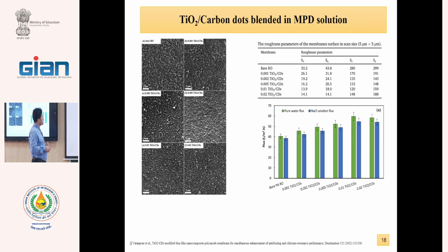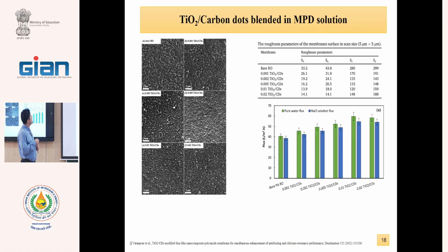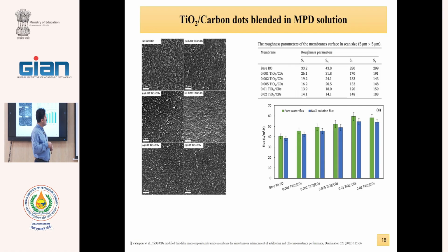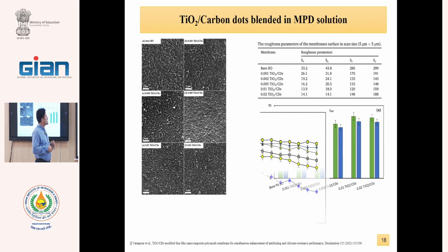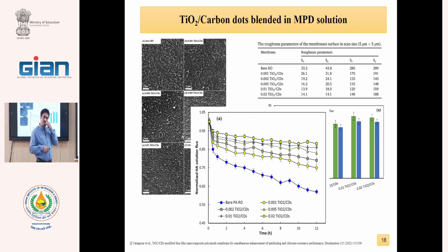Therefore, many papers coupled one organic and one inorganic material. And in this paper, we see with addition of the nanomaterials in a very low amount, the flux relatively increased 50%. And you see, this is no nanoparticle and has a rough surface, but with addition of nanoparticles, the roughness decreases, and the decrease in roughness can improve the membrane antifouling properties.